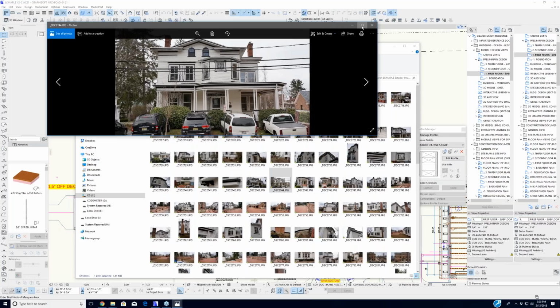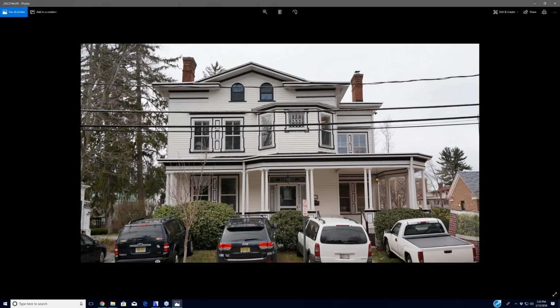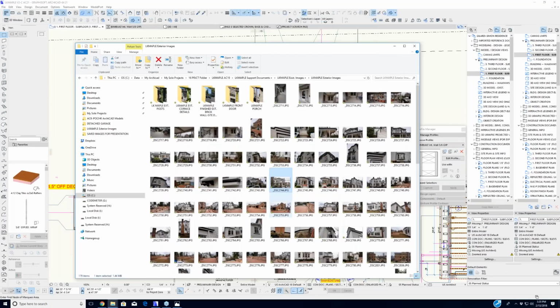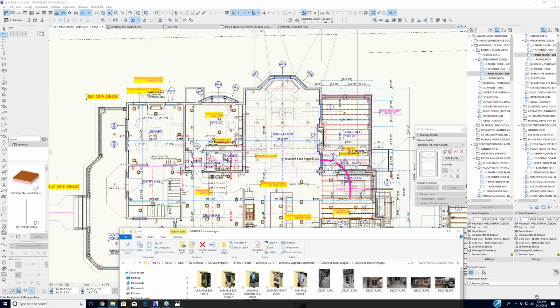So here I'm standing on the street. You can see some of the brick townhomes on the far right side. This is existing. This is taken before we're really working at all. All these cars are here. They're parked for the construction of the townhomes. All of this was documented on site with either a yellow tape or overalls. Obviously, we're done with lasers. And then the entire interior was done by hand. Overalls, height, width, jamb dimensions, door heights, door profiles, door widths. And what I ended up with is all of that data, which is then placed into the model.